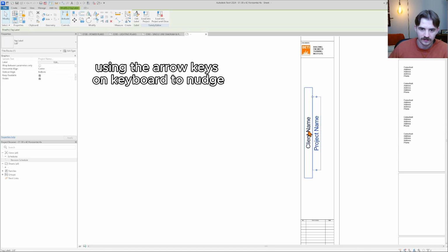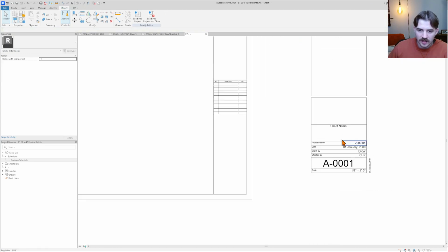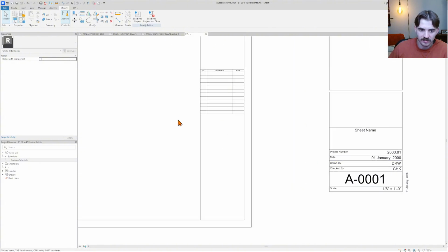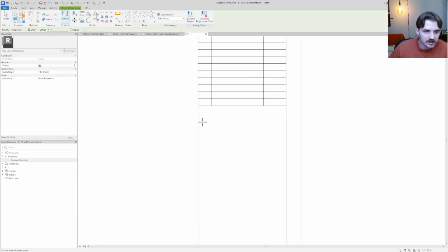That looks good. Okay, and then we can get our project number, our drawn by, and our checked by put in over here. So I'm going to do another line. And again, this is just stylistic preferences. Let's see here. This is 3 inches, right? So I want 3 boxes because I want project number, drawn, and checked by. So each of these would be exactly an inch because it's 3 inches. So 1, oh, I did foot. 1 inch. And that's where it put it out to.